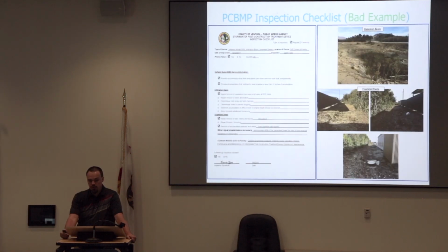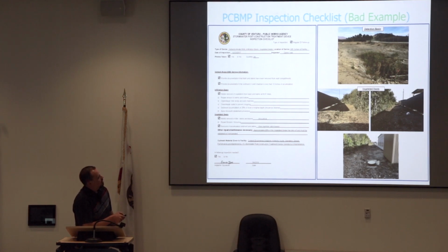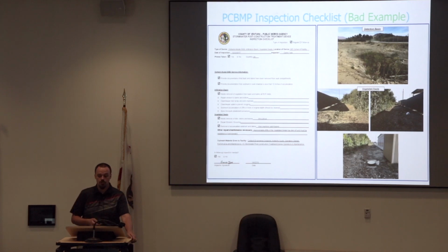This is one that wasn't so lucky. On the right side there at the top, you have a detention basin. All the vegetation's dead. It was vegetated a few years back. The only vegetation that seems to have taken root is at the discharge point of the head wall. So all the water coming in, which tells me that there's obviously some water ponding here, which is why there's vegetation thriving here. And it was clogging or getting into these inlets, so we have to make sure that those are cleared out so we're not actually having issues during a large rain event.